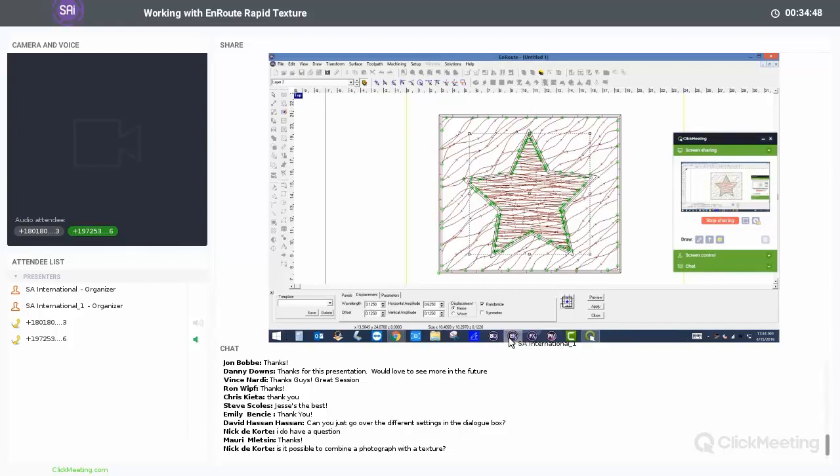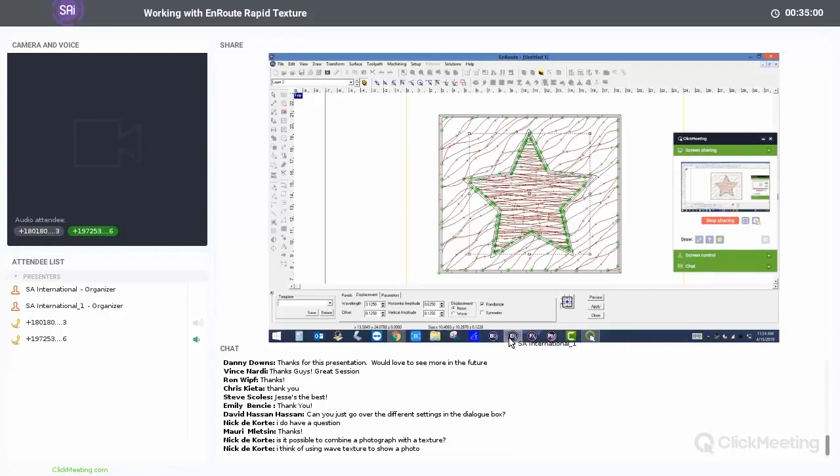When we upped that horizontal amplitude value, we got a very randomized pattern, and it was no longer a true circle. And then your vertical amplitude, this is your Z depth. With noise, it's 100% your depth. With wave, it's 50% of your depth. And then randomized just means you are randomizing the Z-axis, so it will move up and down. And then symmetric, if you were to check this, it would distort your factors just a little bit in order to make the panel actually symmetric.